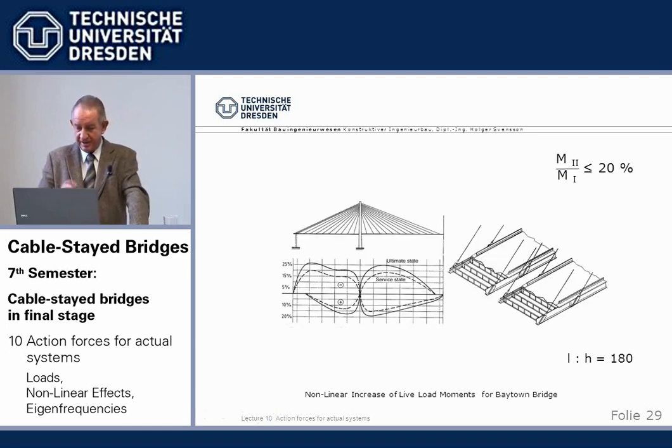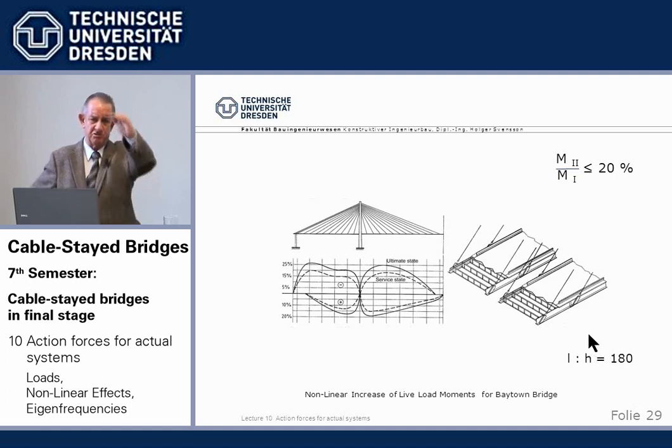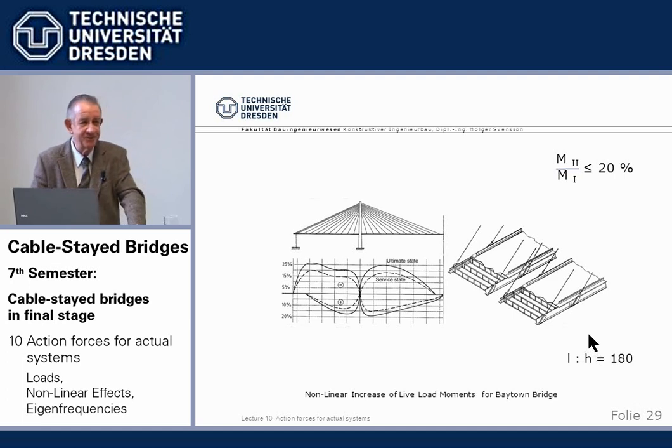Okay, now if we go to something more slender, and that's typical for all the Rhine River bridges, people make strong, heavy box girders and that's good enough. Now, some others, like myself, said no, we can. I showed you the stress is independent of the depth. Let's reduce the wind load. However, we must pay the price in second order.